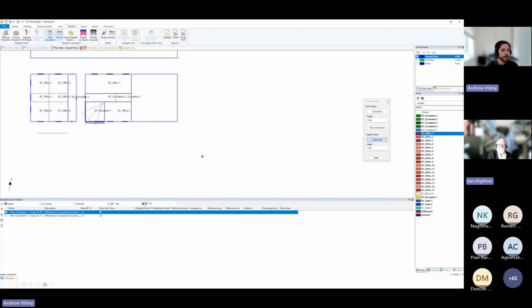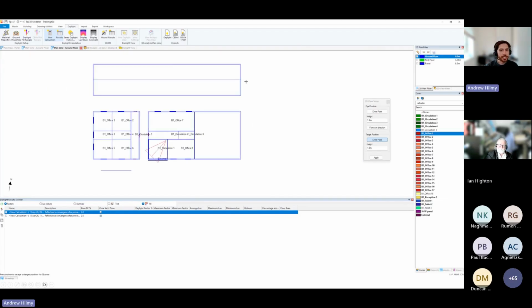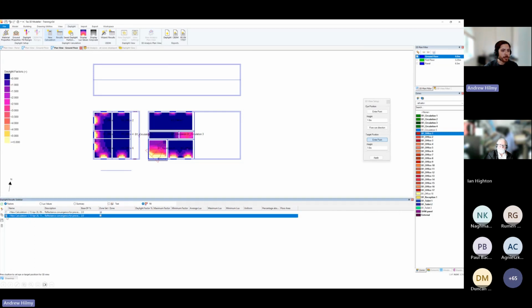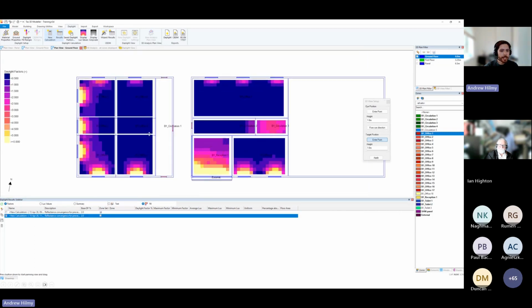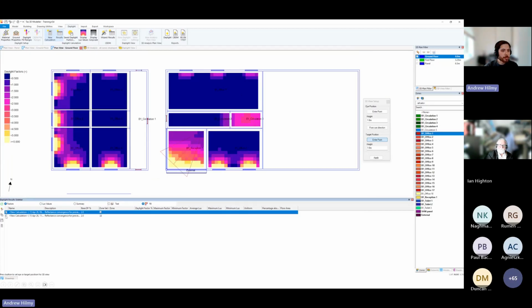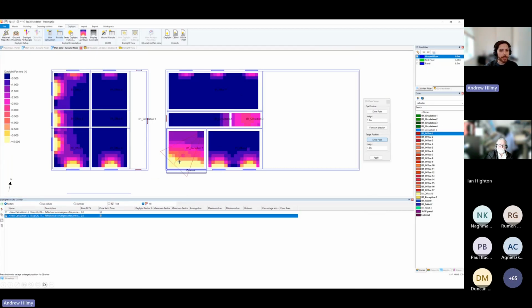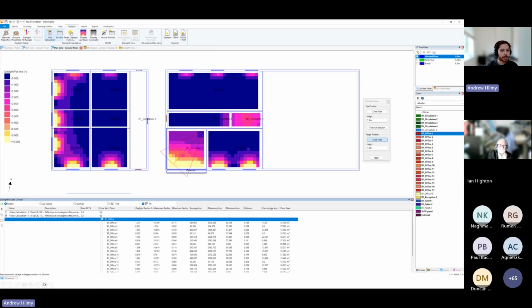Exactly. So once your daylight calculation's finished, that dialog automatically closes on its own. Then it automatically opens the daylight results sidebar here, and you can tick the box here to view the results. And you can have multiple results in a single file, which is quite useful because then you could make a tweak to the model and compare the design. So that's quite handy, and you can set a name for the calculation to help keep track of what you've done. And you have a tabular view of all the results here.